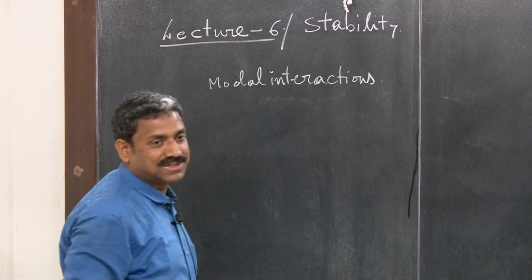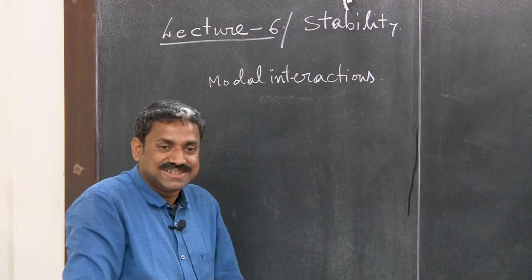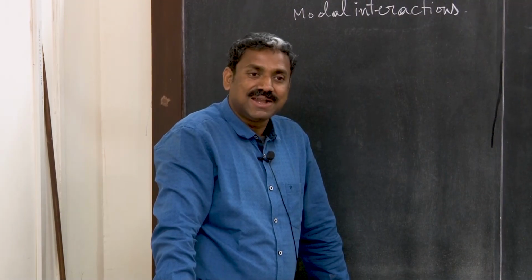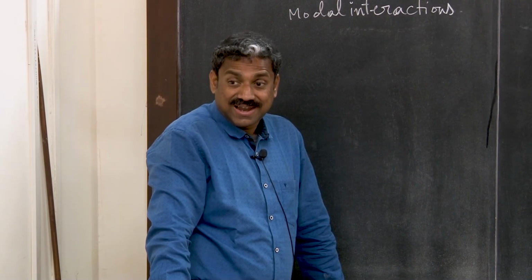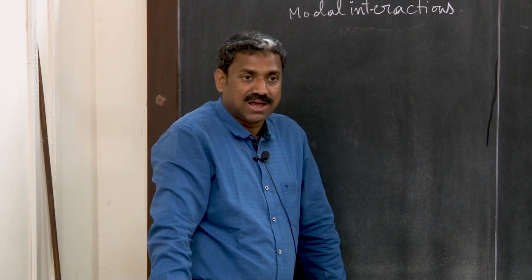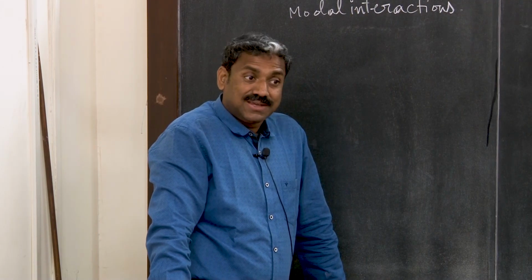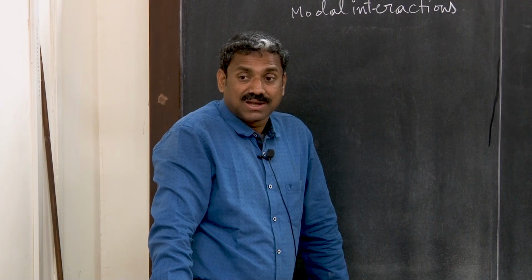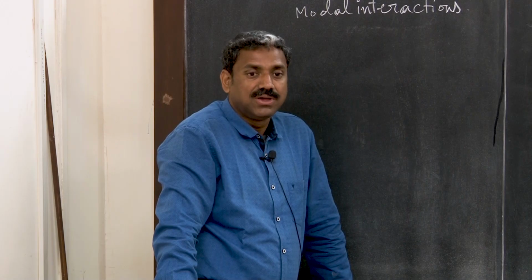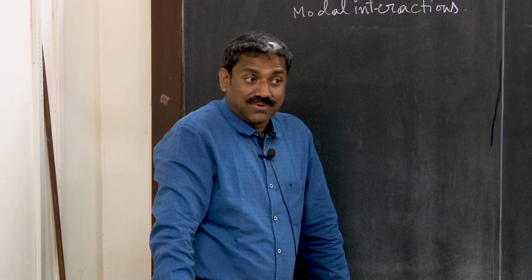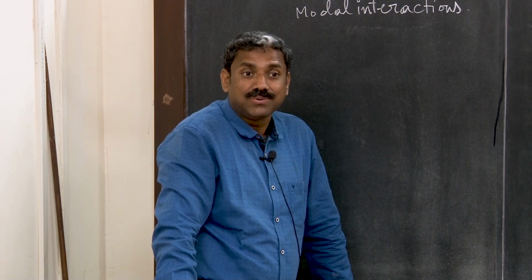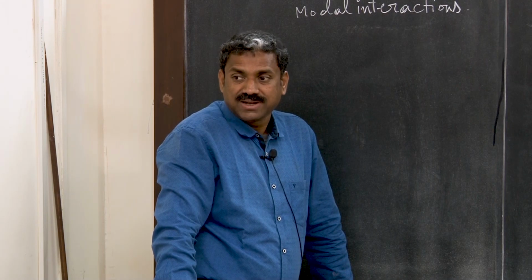But how will I ensure modal interaction? Look, if you do a linearized analysis, that means an eigenvalue problem leading to eigenbuckling, you will get uncoupled modes only. But they are actually coupled. If you consider geometric nonlinearity, higher order nonlinearity, they are actually coupled. So these apparently separated buckling modes are actually coupled, and when you do a linearized eigenbuckling analysis, for shell kind of structures we will see there is a multiplicity of modes, and the modes are very close. That means they tend to interact because they are coupled by geometric nonlinearity.